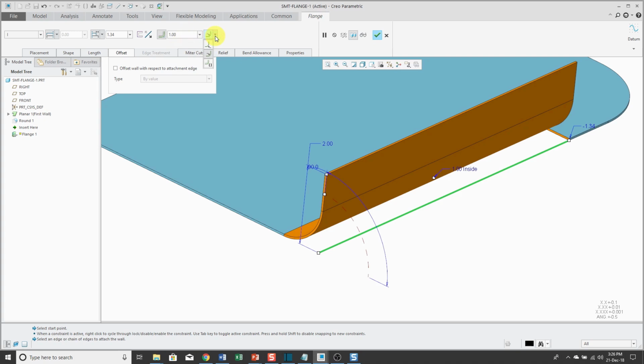And the next drop-down list controls whether you are dimensioning to the outer surface of the bend or the inner surface of the bend. And you're probably going to use the inner surface because that's what sheet metal manufacturers are usually going to bend to. That's a bend machine that they're going to look at. And also you could use the parameter value sheet metal default radius side. And I'll go more into some of these different parameters later on.